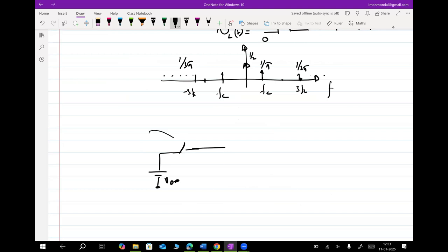So this comes from the mixer. This is a square wave. So if you do this, you are going to radiate all other frequencies also. So you cannot do that. Which essentially means that you need a filter here at the output and then transmit it to 50 ohm, to the antenna. 1 second.